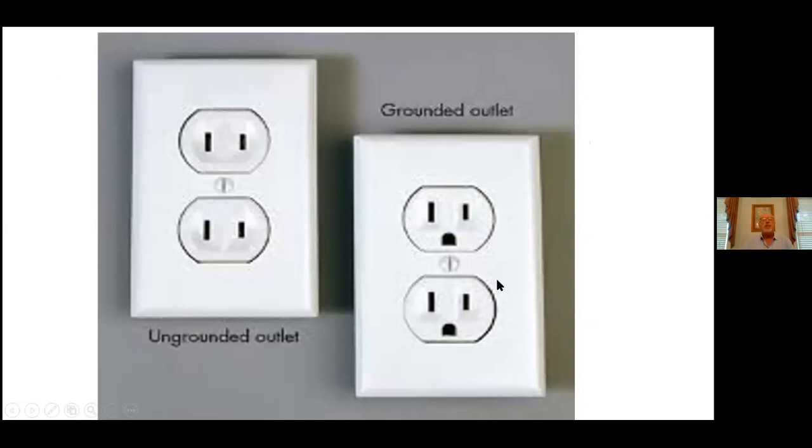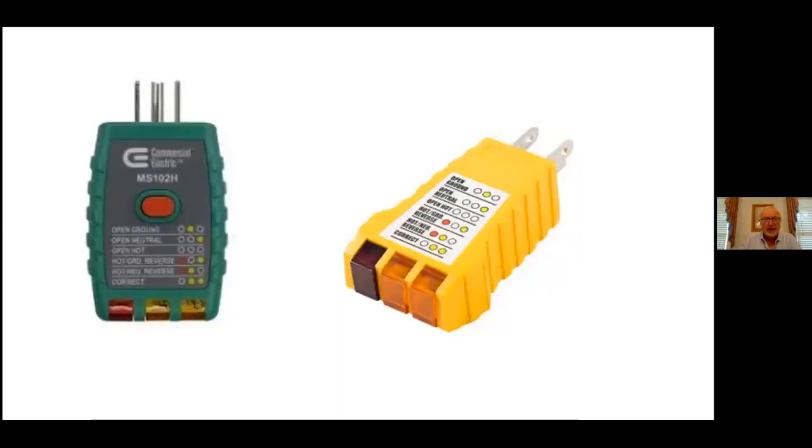And that's why we do our inspections at Home Probe by testing every accessible outlet, simply because many times these electrical outlets have been changed during a renovation, but the wiring has not been changed and the outlets are not actually grounded. So what happens then is you plug in your computer or your very expensive TV, and there's a power surge through a lightning strike, and your system is totally fried, simply because you thought you had a grounded outlet and you did not. So the way you can check that is by having one of these testers.